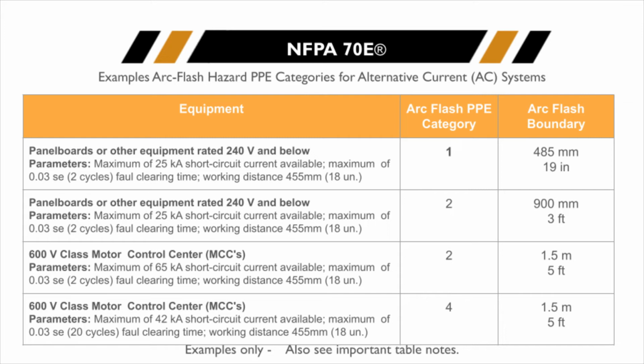And the text says when the back of the head is within the arc flash boundary, you have to wear PPE. Many people have trained themselves to turn their head to the side when they switch a breaker or a system on or off. So think about that. Did we just possibly put the back of our head or the side of our head in the arc flash boundary and we have no balaclava on? Again, this is where it's important for us to perform risk assessments.